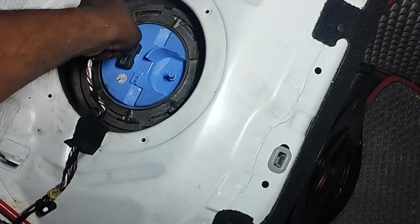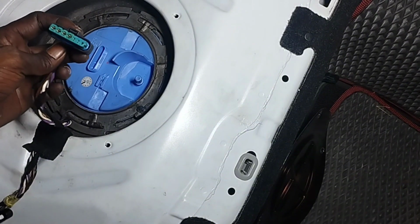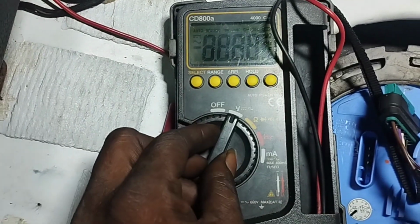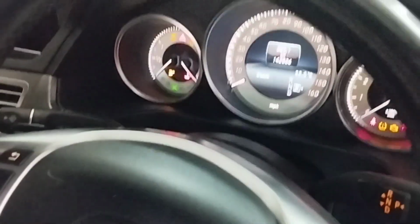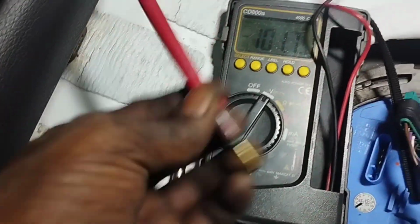First I will remove the fuel pump wire socket to test the fuel pump circuit. After opening the fuel pump wire socket, I set the multimeter to DC voltage. After setting the multimeter to DC voltage, connect the black wire to the car body earth. Step number 1, to check the fuel pump positive supply voltage, place the ignition key switch in the on position.